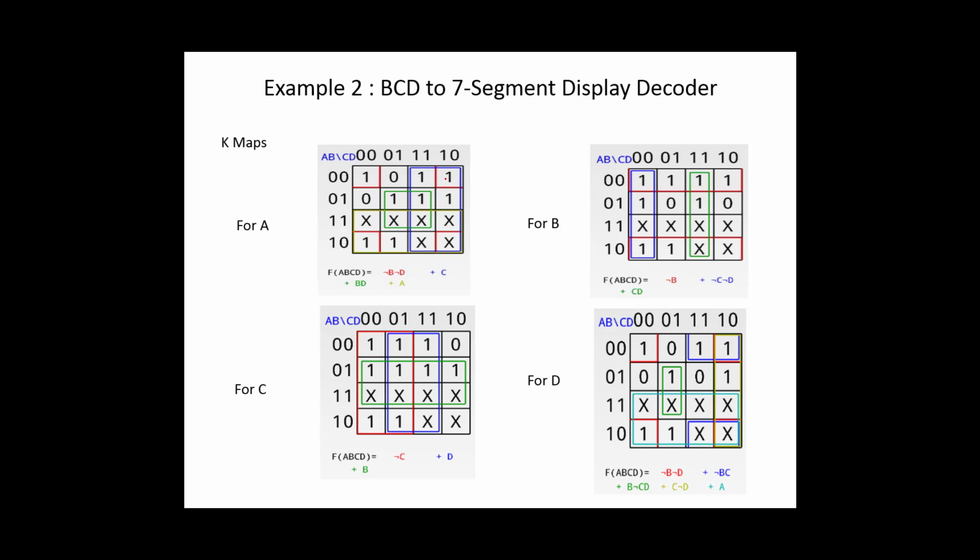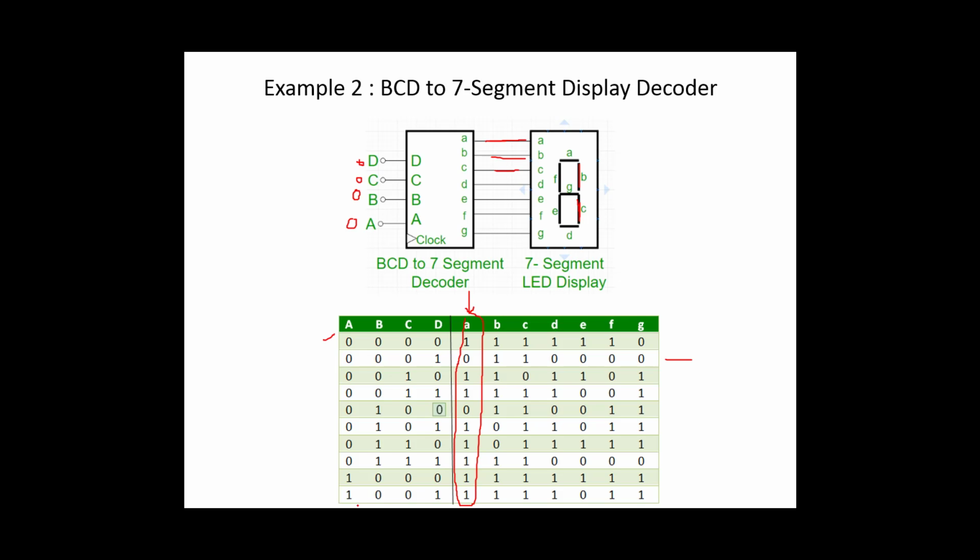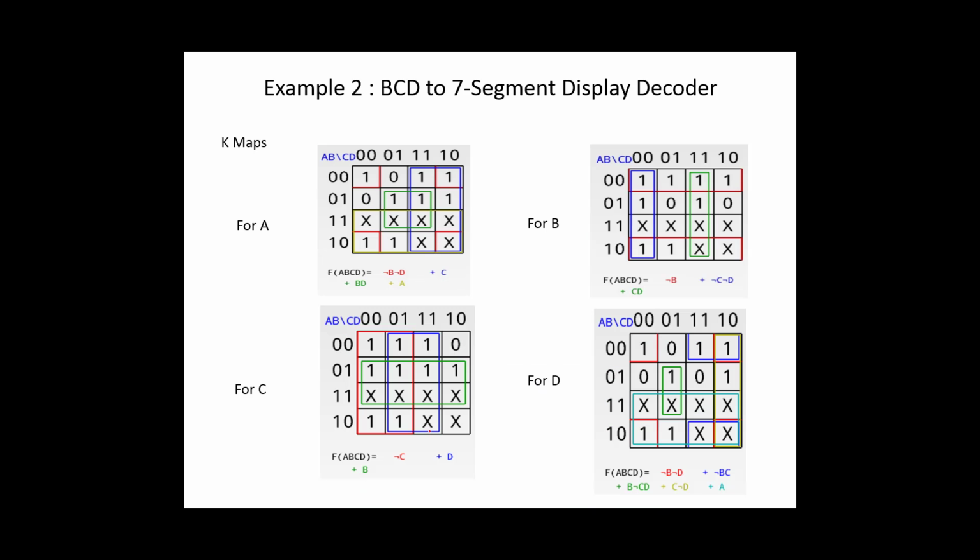After we have placed 1s over here, as we know that for 4 bits the total number of possible input combinations is 16, from binary numbers 10 up to 15, these combinations would be treated as don't care conditions. So we can place X for them in the K-map, and this would help us in making groups of ones to further simplify the boolean expression.